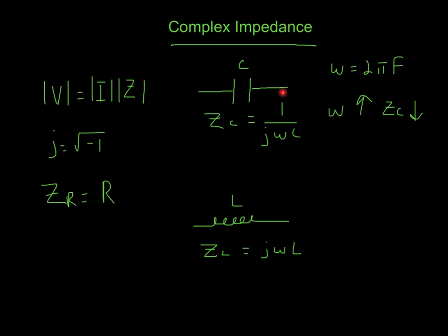And sure enough, if you remember, the flow of current for a capacitor becomes greater and greater the quicker you change the voltage across it. And the quicker you change the voltage across it, that's related to the frequency going up. So imagine I go positive, negative volts, and then I flip the battery and I go negative, positive, positive, negative, negative, positive. The faster the voltage changes across this thing, the more current that flows through. Another way to look at that is that the more current flowing through this thing, the smaller the impedance is. So you get that?